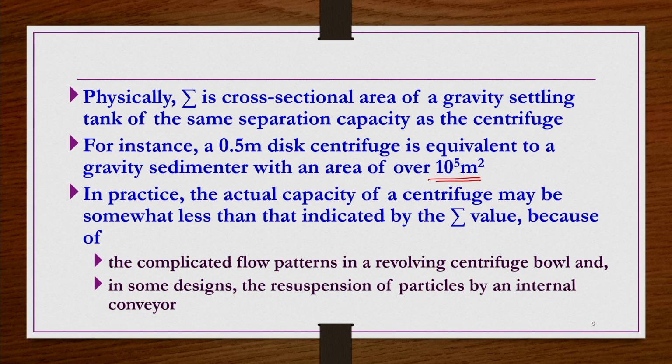In practice, the actual capacity of a centrifuge may be somewhat less than that indicated by the sigma value because of the complicated flow patterns in the revolving centrifugal bowl, and in some designs the resuspension of particles by an internal conveyor may also take place, but these discrepancies are not going to be too large from the calculated values anyway. So, now we see some examples.